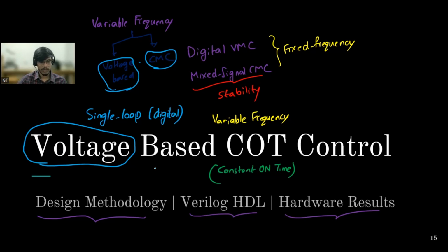Sir, this current mode control, in the sense of peak current, constant on time, constant peak off time, peak or valley. In that case, both voltage and current will be controlled, right? Yes. Controlled in the sense that we'll have two loops, so we can monitor both current as well as voltage. We can put either a peak or a valley on current, as well as regulate the voltage at that particular value.